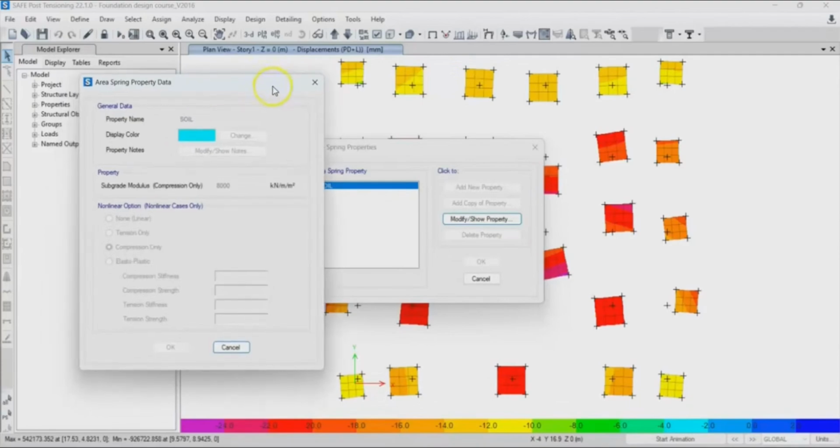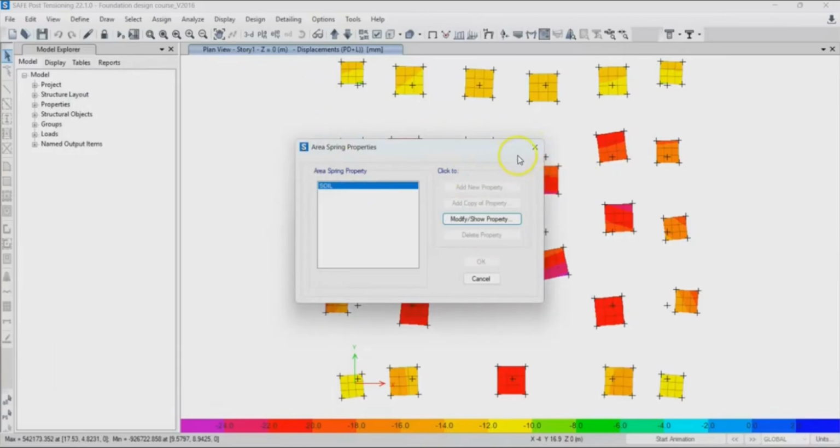And it is going to be able to resist or withstand the pressure that is coming from the column, right? So meaning in that case, your footing is going to settle less, which is going to reduce the differential settlement for the neighboring columns. Okay, so these are the different ways you can pass the differential settlement check.